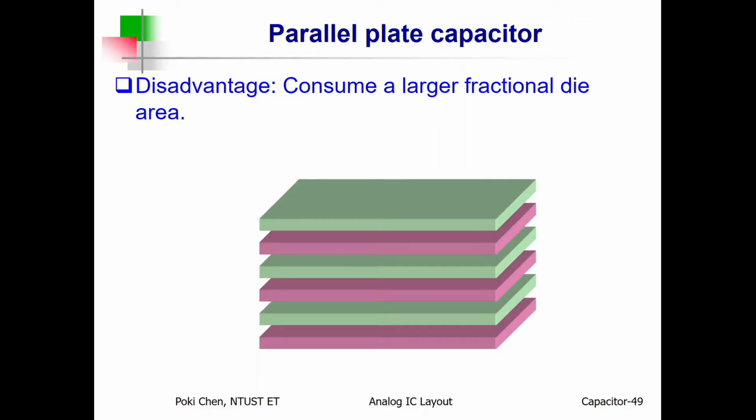In the past, as I mentioned in the previous chapter, for the previous paper, we had such a very old style horizontal parallel plate capacitor. It depends very, very much on vertical flux. It is not scaled with the process, and also the accuracy or the matching is really poor.